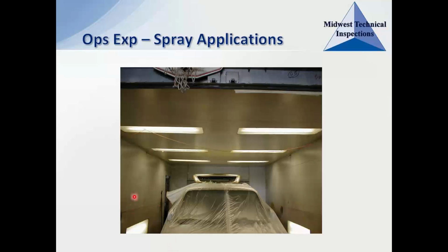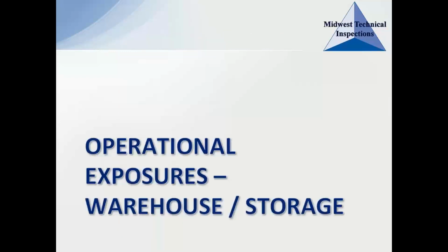For this one, you can see it looks like they just have standard drywall on the wall, so that would be something that would absorb the overspray, so it's not necessarily ideal. But the big concern that we have here is that they have this electrical cord that they have run into this facility because they were bored in there. They wanted to hear music, so they ran an electrical cord from outside into the booth so they could play their music. Now, there's a reason there's no outlets or switches inside of the booth, and it's the same reason to keep that radio outside of the booth. We don't want anything to possibly ignite those vapors.